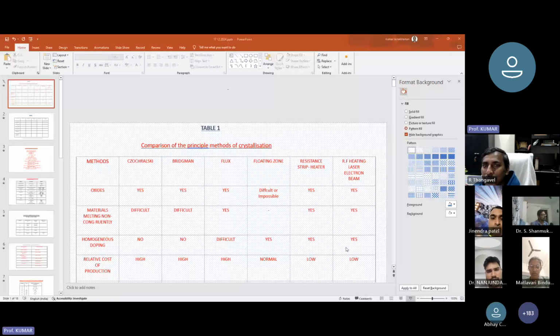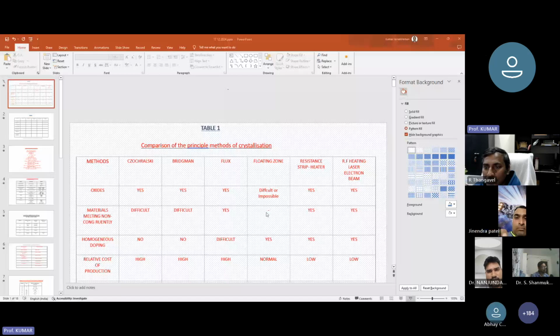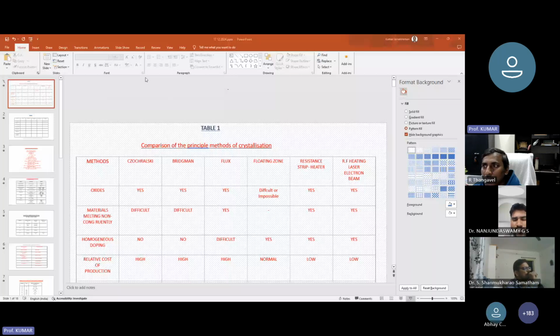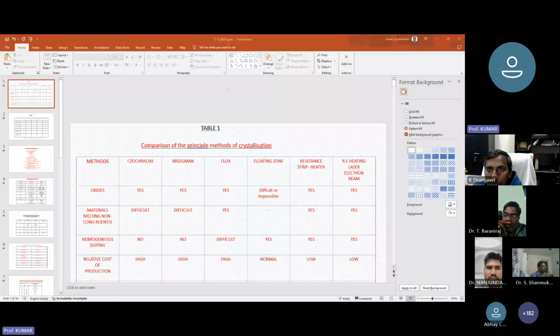Okay. So you know that I told about Czochralski, then about Bridgman, where the crystal will be grown inside the crucible, whereas in Czochralski we try to pull the crystal out of the crucible. This is the major difference between these two. Here there are some big advantages, like you can grow large size of the order of 600 kilograms, whereas in this it is very difficult to have a container which can hold these 600 kilograms of material. So generally it is about let's say something like 2 to 3 kilograms in Bridgman.